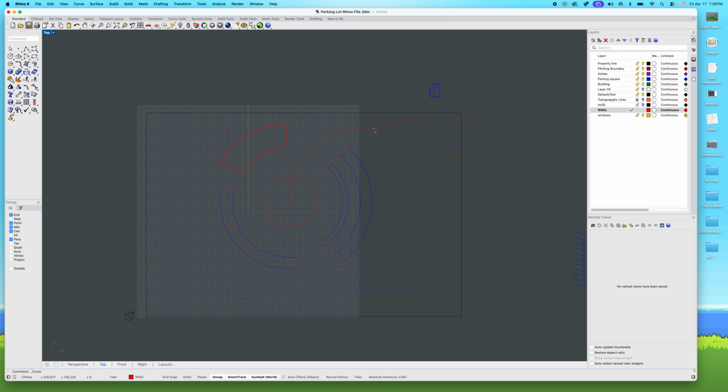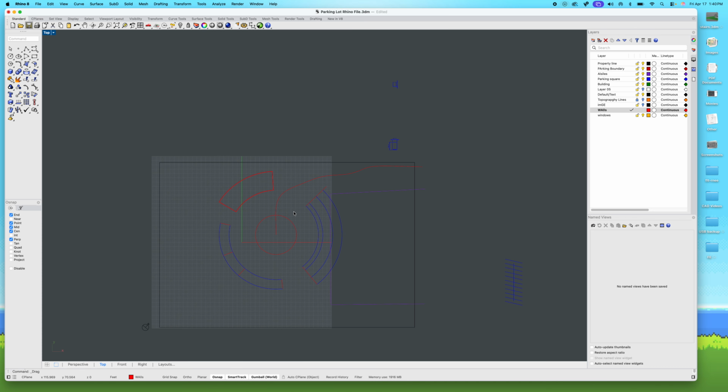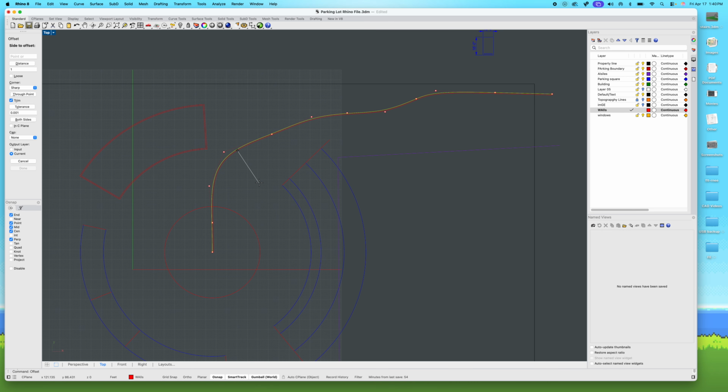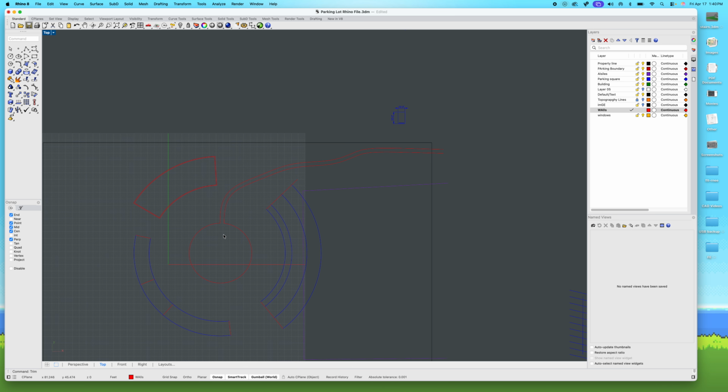But another thing that's nice about this is it brings us control points, something that I can also manipulate and vary. Making some sense? It's looking a little funky. You can also offset these too. Let's say this was a sidewalk, for goodness sake. Let's say it's 6 feet, and voila, I have a 6-foot sidewalk. Maybe it actually terminates here. See what I mean? So not too bad, right?